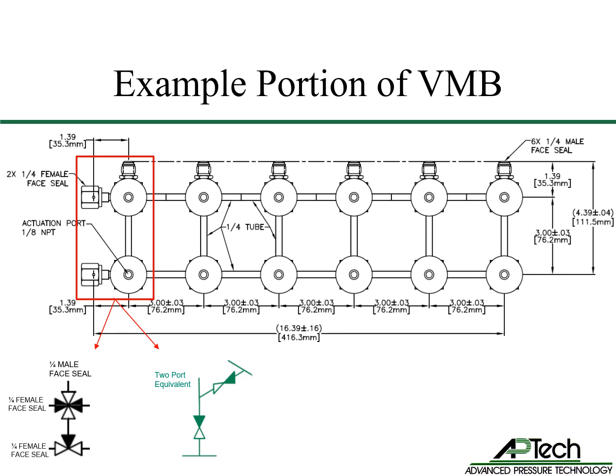The outlet ports are 1/4 inch female face seal at 9 o'clock and the 1/4 inch tube stub located at 3 o'clock. When this valve opens, purge gas flows from the 1/4 inch female face seal to the 1/4 inch male face seal port located at 12 o'clock and the tube stub at 6 o'clock. This is a common example of a valve being used in a reverse flow direction from standard. In the example, the outlet ports are being used as inlet ports and the inlet ports as outlet ports.